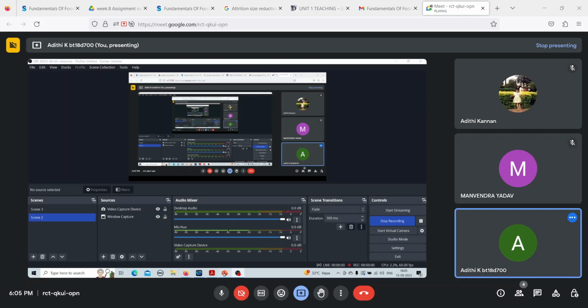So hope this is clear. You will have multiple stacks of sieves. You will pass the food particle on the top. You will keep shaking it. Smaller the particles, more it will be able to pass through the sieve and be collected in the pan. If it is large enough, it will be retained in that particular level itself.